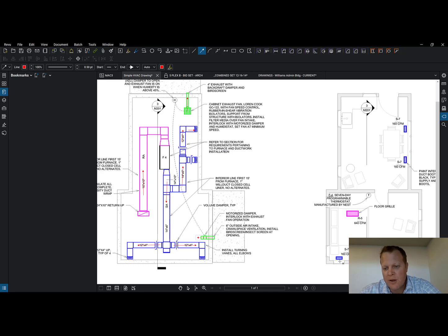Okay, now if we went over here, what direction is the air coming out? Well, it's coming out in lots of different directions on this, let's call it diffuser register. So it's going like this, and all the air is coming back into this thing. How do I know? It's a grill, and it is in the same space as this return, so I know that this is negative. All the air is pulling into here.